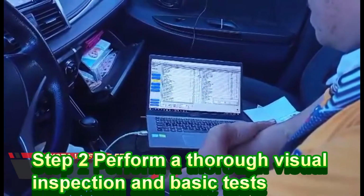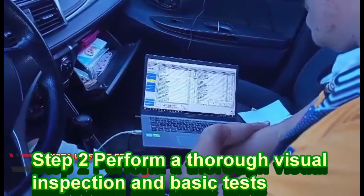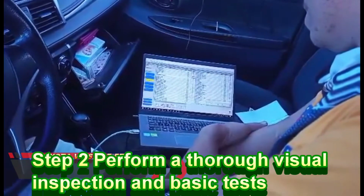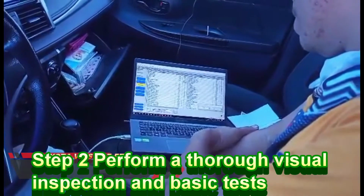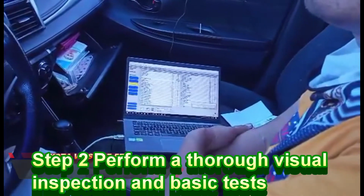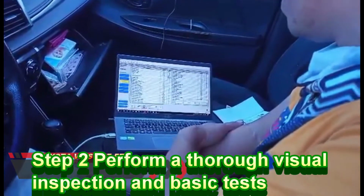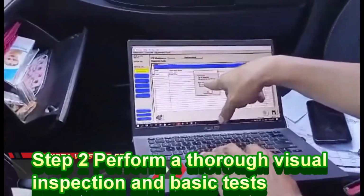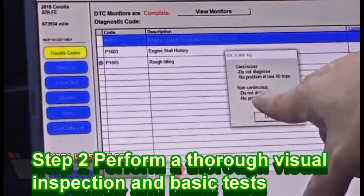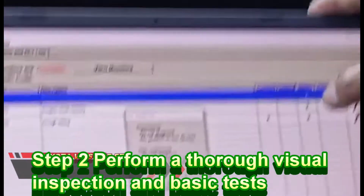Check the air cleaner and air duct. Squirrels and other small animals can build nests or store dog food in them. Check everything that does and does not work. This step involves turning things on and observing that everything is working properly. Look for evidence of previous repairs. Anytime work is performed on a vehicle, there is always a risk that something will be disturbed, knocked off, or left disconnected.